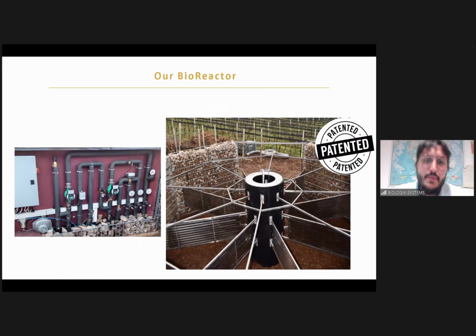So the second aspect of the technology of the solution is the bioreactor. The bioreactor, which we see here, is a technology where the composting process is done. As you can maybe see, it is not a simple compost heap. There is some technology inside. We have a heat exchanger, as we see here. Later, there are some condenser plates. We have controlled aeration, controlled humidification, and so on. So this technology makes the extraction of heat from a compost process efficient.